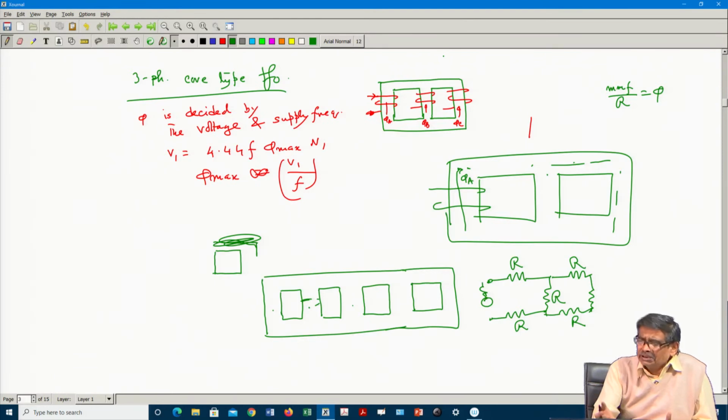In case of a 3-limb transformer, what happens? These third harmonic fluxes, if at all any, because of the magnetizing current problem or because of some unbalanced current flowing on the secondary side, will have positive, negative and zero sequence components. Zero sequences are cophasal.